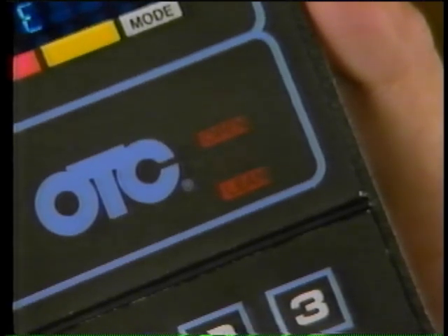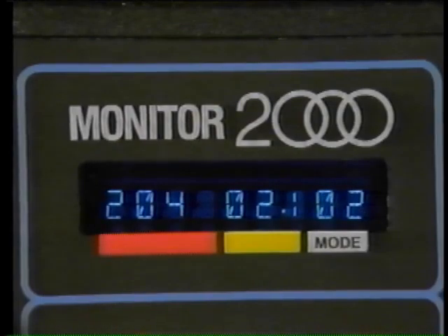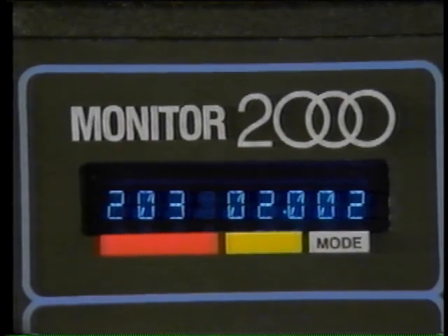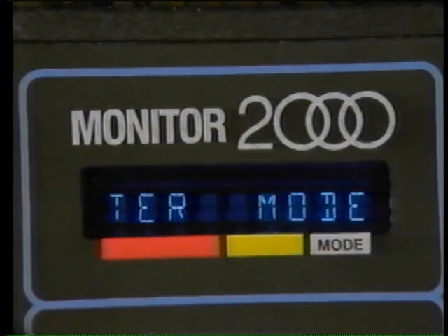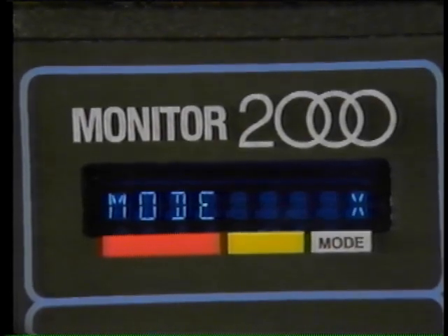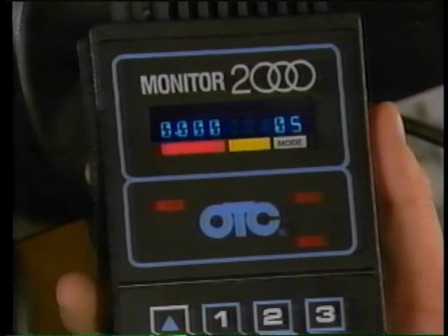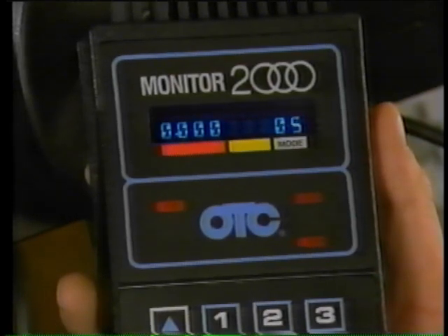So you move on to Step 2 in the diagnostic chart. Step 2 tells you to disconnect the wiring harness from the O2 sensor, then jumper circuit 412 of the harness to ground. The scan tool should display O2 sensor voltage below 200 millivolts with the engine running. Since you're still reading coolant temperature, you'll have to change modes. So push the mode button and enter the new mode number. Now the O2 sensor voltage will appear on the display, and it is below 200 millivolts. This indicates the circuit leading to the O2 sensor is good.